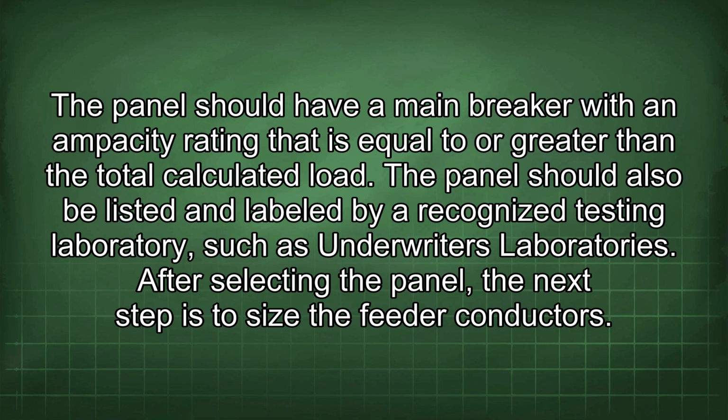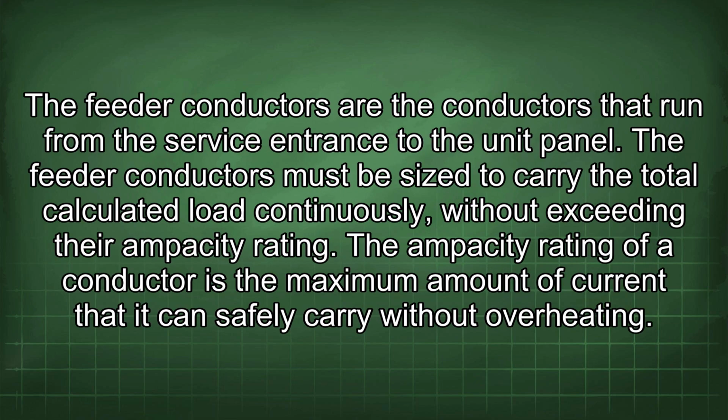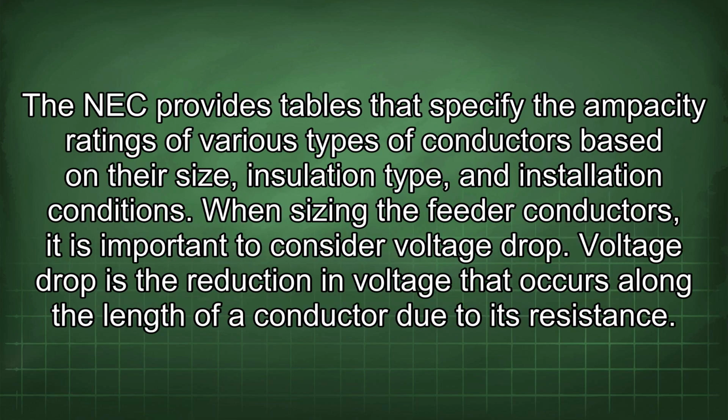After selecting the panel, the next step is to size the feeder conductors. The feeder conductors are the conductors that run from the service entrance to the unit panel. The feeder conductors must be sized to carry the total calculated load continuously without exceeding their ampacity rating. The ampacity rating of a conductor is the maximum amount of current that it can safely carry without overheating. The NEC provides tables that specify the ampacity ratings of various types of conductors based on their size, insulation type,